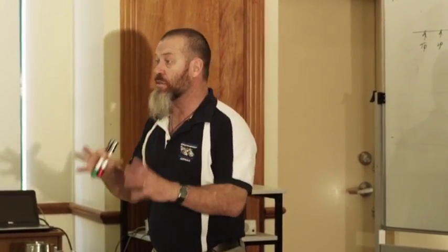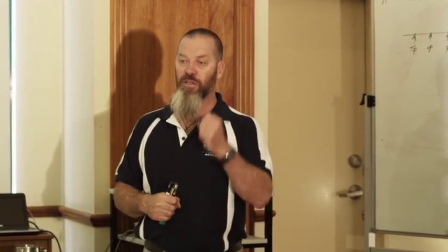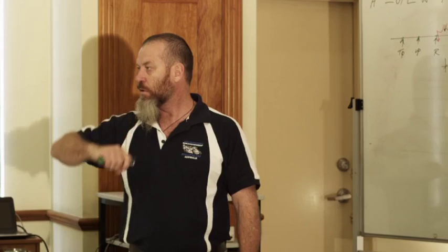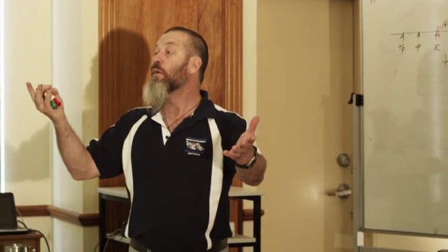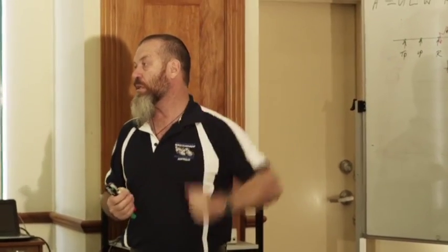So when you're doing an assessment of a connection, the first step is you look at it and say, is this an outside wall connection? Yes or no? Simple as that. Is a lintel plate an outside wall connection? Yes. So the formula I use is DBC divided by 2 plus the overhang.